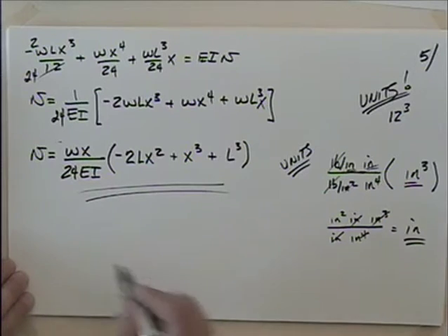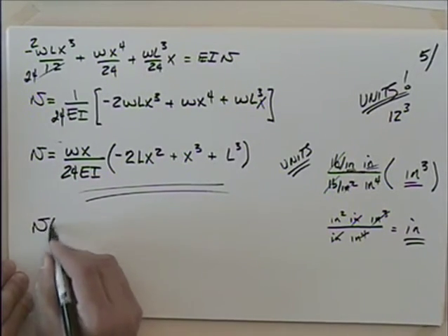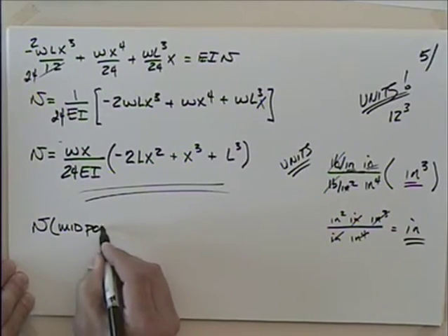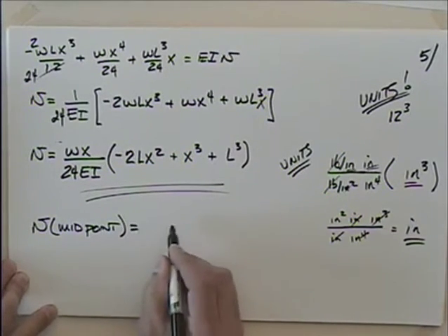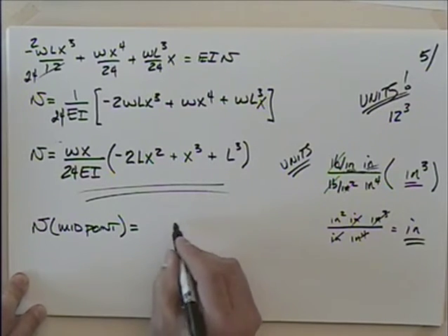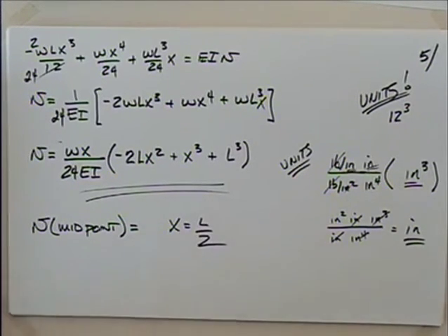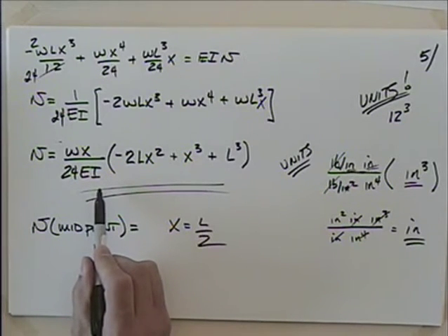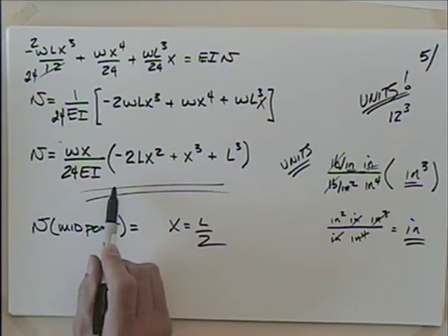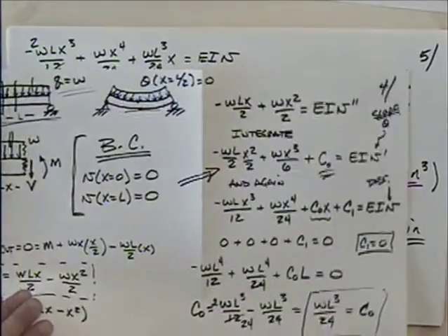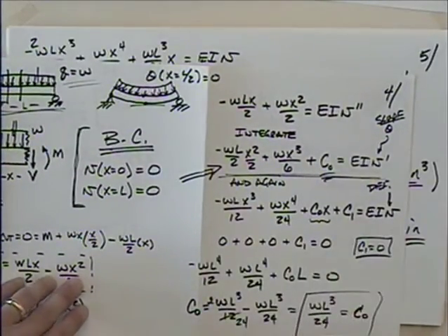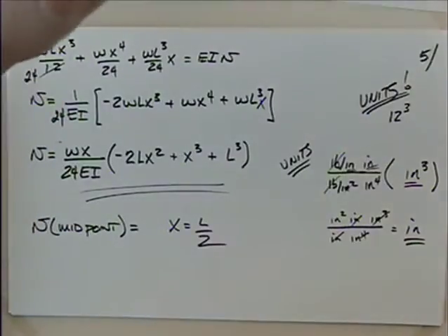What if we wanted the deflection at the middle? Yeah, x is going to be equal to L over 2, isn't it? Just go through that. And what if you wanted to know where the maximum deflection was? You could differentiate this thing, right? But before we break out the calculus, we already have it differentiated. What's that called? It's called the slope, isn't it? And we'll find that the maximum is where the slope is equal to 0. So it shouldn't surprise us that in that particular case, the maximum is in the middle also.